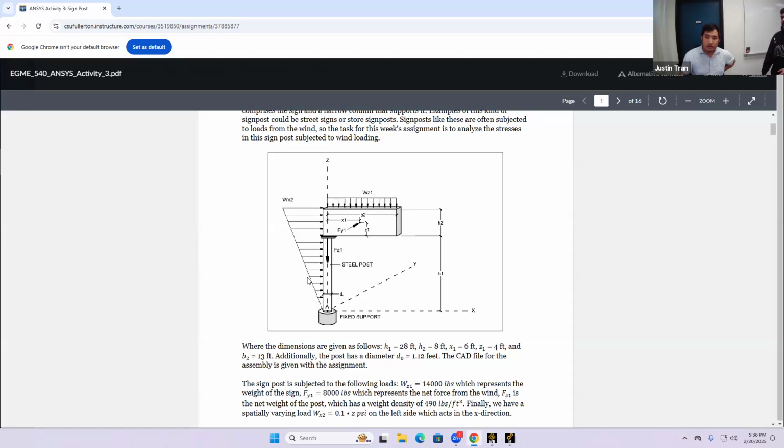So this is a very common tactic, and a lot of times when you're applying forces in a finite element simulation, the geometry itself is not going to be conducive to applying the force in the exact place that you want. And so oftentimes you have to create some extra surfaces or some extra models in order to apply that force. Okay, and that's what this is about.